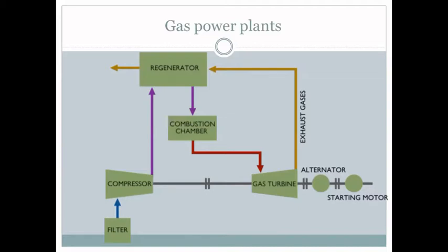In the turbine, the compressed air is suddenly expanded, hence it gains kinetic energy, and because of this kinetic energy, the air can do mechanical work rotating the turbine. In a gas turbine power plant, the shaft of the turbine, alternator, and air compressor are common. The mechanical energy created in the turbine is partly utilized to compress the air.